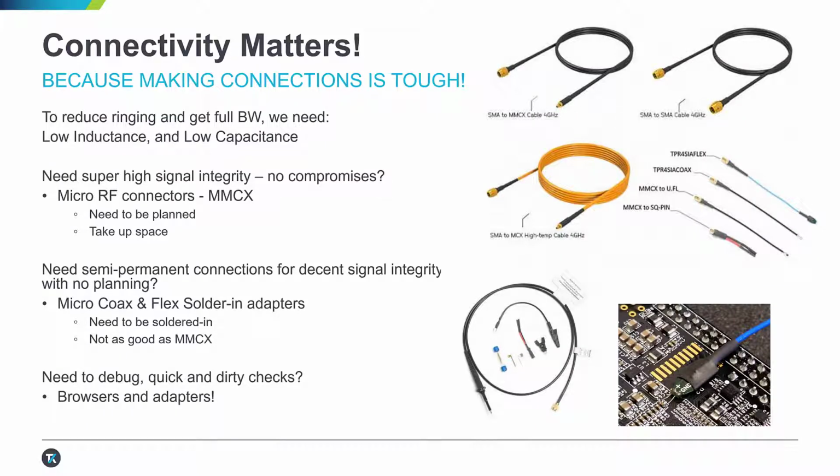All right, now one of the key aspects in making these very precise ripple measurements has a lot to do with the connectivity options that you're going to use. At Tektronix, the power rail probe that we've developed, the TPR 1000 and 4000, uses a bare SMA female connection. So we offer many of the probe tips that we show from that SMA out to different leads. And again, the goal for us is to offer the most convenient, lowest inductance and lowest capacitance tip that's available out to the full bandwidth of what's required.